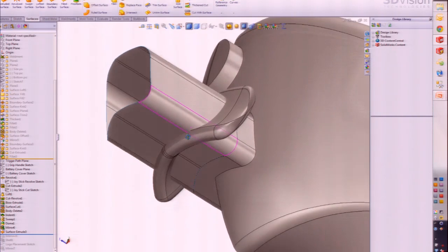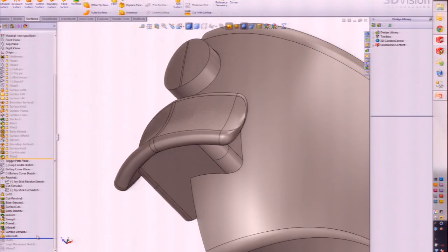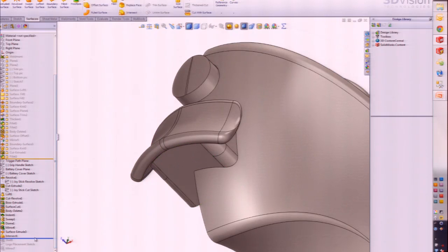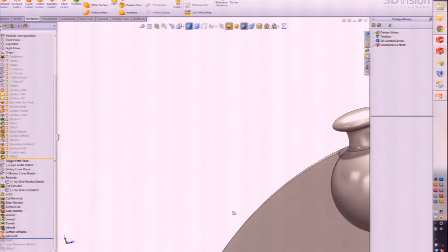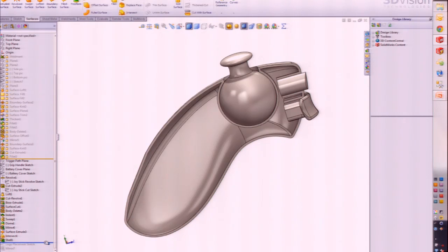What I just did was I bounded all those bodies and that little sliver where there's that void of geometry. With the intersect feature that I'll show you in detail in a little bit, what it does is it takes all those bodies and that surface, combines them all together, and fills in the voids, all in one shot. Okay, so very, very powerful multi-body command using both solid bodies and surface bodies. All right, I'm going to shell this out, and then I'm going to go ahead and mirror this across.